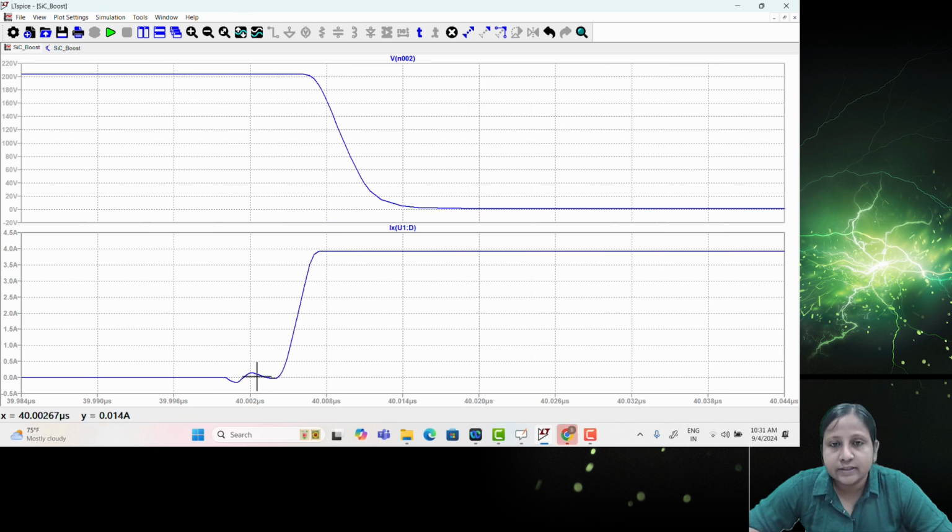A very small oscillation is there, in this particular portion, that is due to the capacitance, and if the switch has any inductance inbuilt to the switch, due to that, but not due to the parasitic inductance in the converter path, right? So this is also a clean kind of waveform, but this is not what you can see in practical operation. That is why this is good for a basic understanding of the network, how the circuit should behave, but it is not useful to generate or to see the noise level present in the circuit.